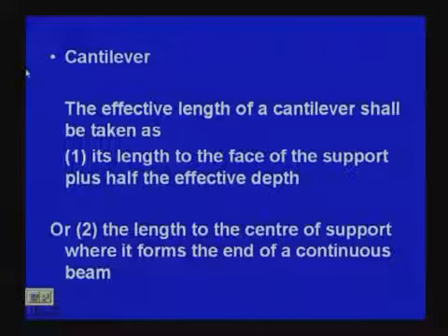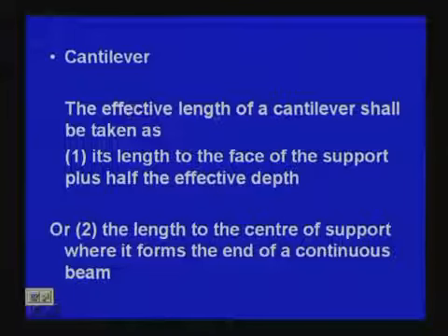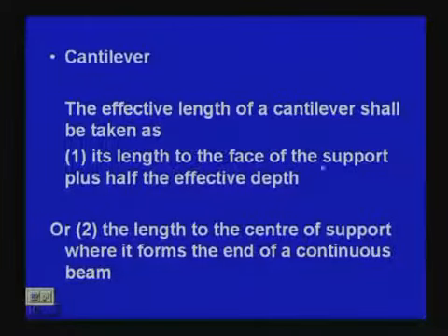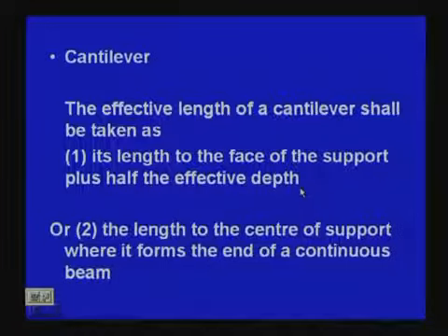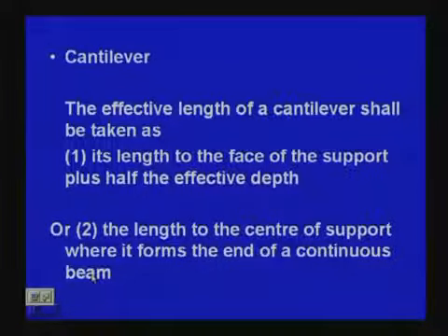Now, what about the cantilever? For cantilever, the effective length of a cantilever shall be taken as its length to the face of the support plus half the effective depth. Please note, in a few cases we are taking effective depth, and in a few cases we are taking half of the effective depth. So, please note that. Or the length to the center of support where it forms the end of a continuous beam.